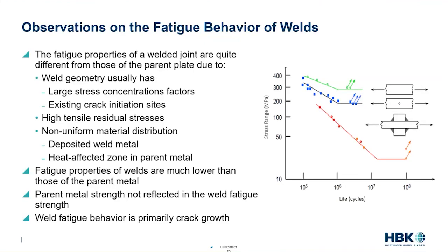As I mentioned, when we look at welds, the fatigue behavior is much lower in strength than the metals being welded. And you can see that onto the right where we have some representative stress life curves. The top curve in green would be representative of a tensile specimen where I have pure material and I've gone off and tested it. As I take that material and basically build a part of it and start to build in certain stress risers, we expect to see the behavior change some, and that's what the blue curve is. The blue curve represents part with some stress risers.